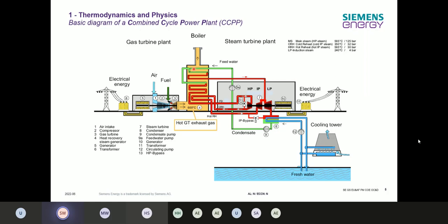In the boiler, we normally have some preheaters preheating the system. In detail, we will go through your power plant later on when we go through the system. So the general process for producing steam is: one time for preheating, then we have an evaporator, where we produce our steam. And after the evaporator, we have a so-called superheater, where it's only steam in, and then the steam goes, for example, to the HP part.